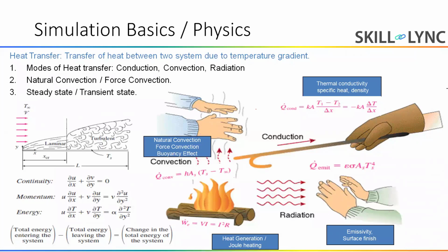When we consider the modeling of this phenomenon, we cannot model a cable length of more than, say, 1 meter. So we need to isolate the cable, do the cable modeling analysis, and then put equivalent boundary conditions on the cable end to draw the same amount of heat.